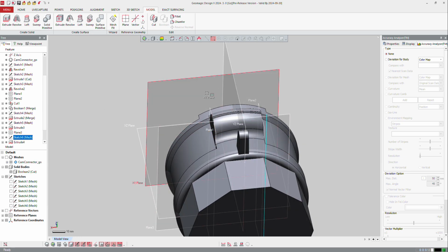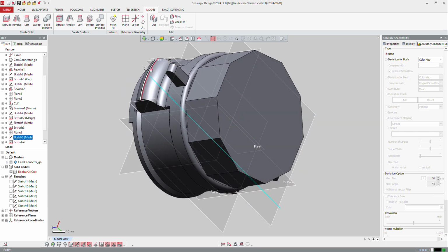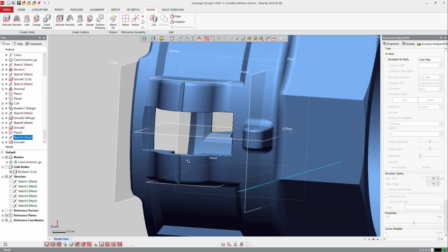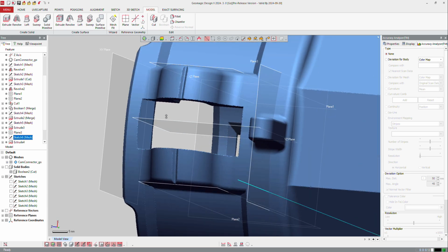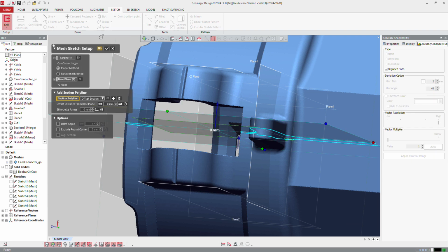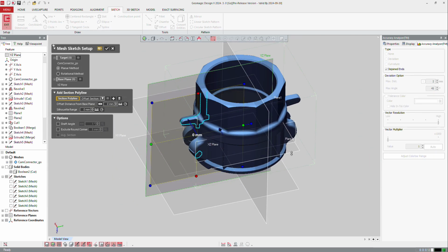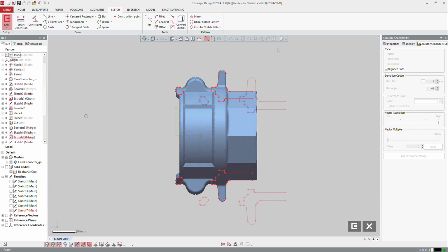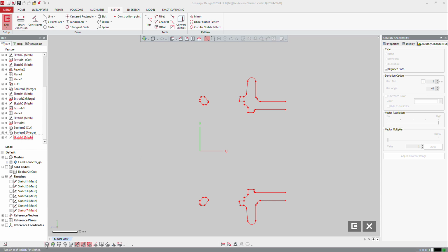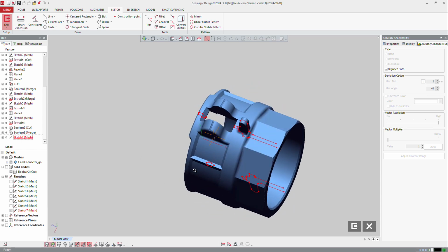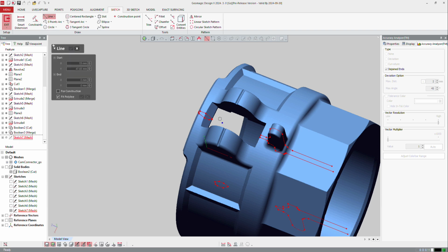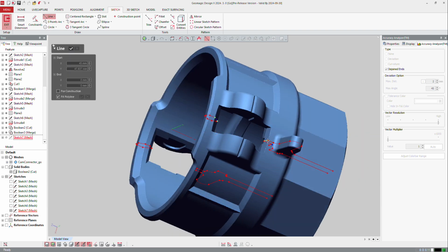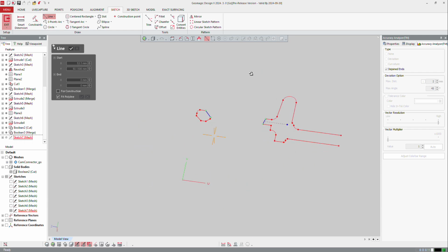Now, if I continue on that, I will finish with this shape, with the opening there. So again, if I look at the cloud here, I got an opening there. I will just make a mesh sketch here. Again, I will make both directions because I don't have mirror. And so now I will create the curves. So of course the curves have to be done in there. So I need to create that line. So I will create lines here, that one there, and the same on the other side. So I can make just that one, and I will make a symmetry on the other one.